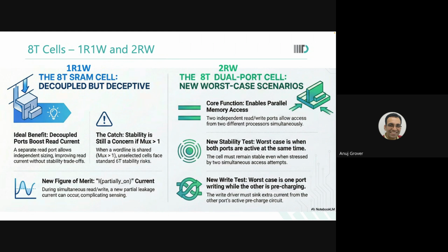So now let us say this particular, the 60 part, the right port. Let us say you have implemented it in mux 4. So in every row, for every word or for every IO, there are 4 cells, of which one of them you are writing. But the word line of all of them is selected. So the remaining all 3 are in read mode.